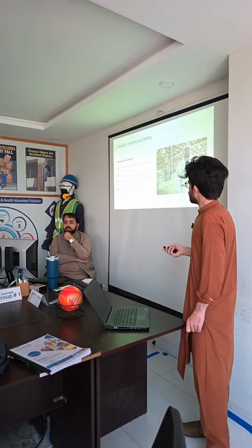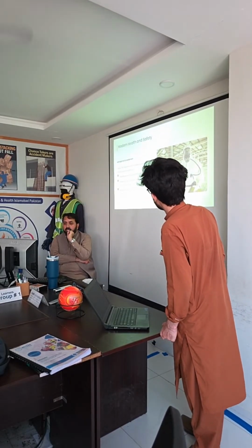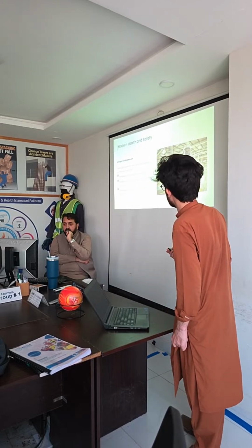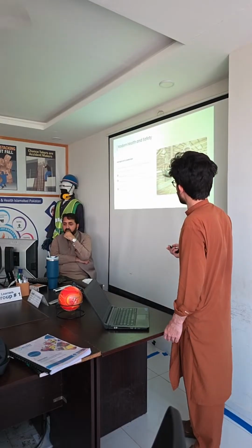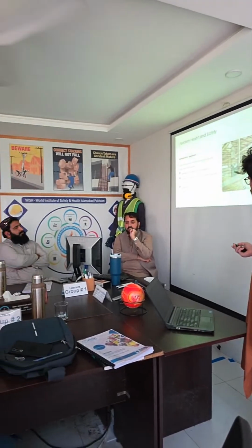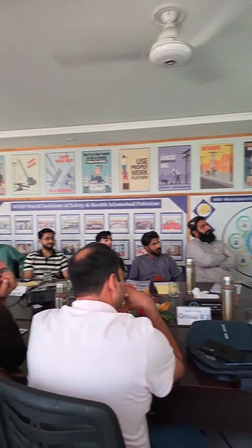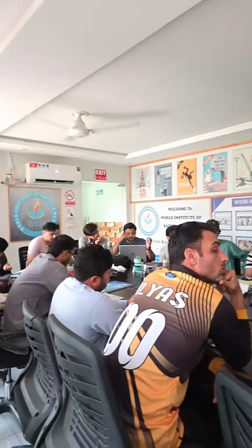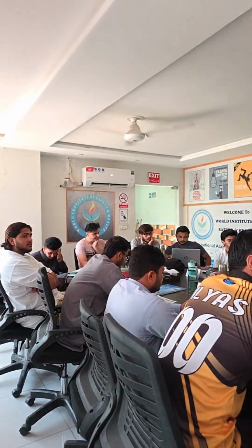Modern health and safety management and abatement. Abatement means removing. Today, the HSE focuses on strictly managing or removing existing asbestos materials. In workplaces nowadays, we try to identify asbestos and safely dispose of it from the site.